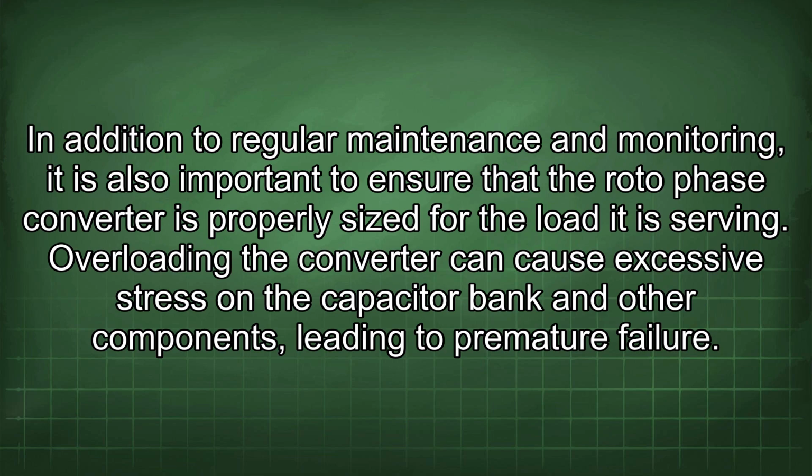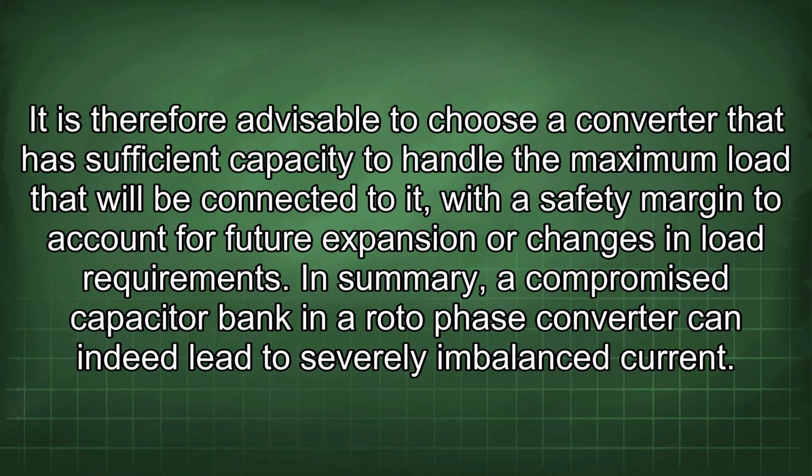Overloading the converter can cause excessive stress on the capacitor bank and other components, leading to premature failure. It is therefore advisable to choose a converter that has sufficient capacity to handle the maximum load that will be connected to it, with a safety margin to account for future expansion or changes in load requirements.